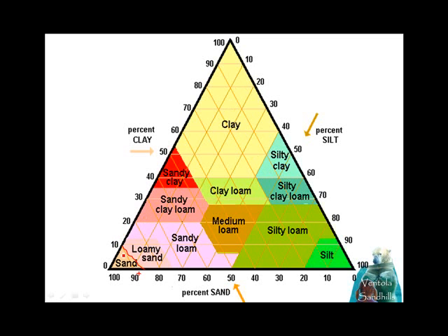If something has even 50% clay, it's going to act like a clay. So let's take a soil, let's take something that's 20% or 25% sand, and that will go up there, and it's 30% silt, it is going to act like a clay because it's going to have 45% clay. So that would be that soil. And you only need 2 parts. And we're going to show you how to do that in lab, how to measure how much sand, silt, and clay. And it works nice because they're particle sizes and they settle